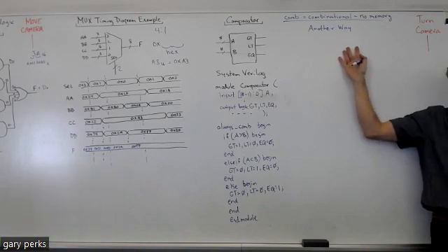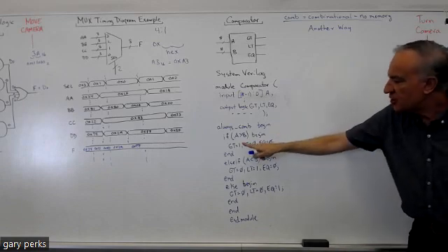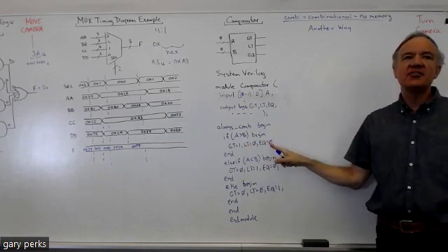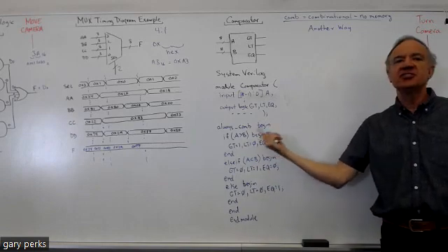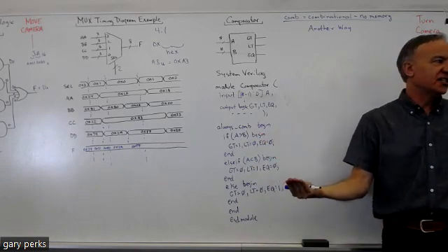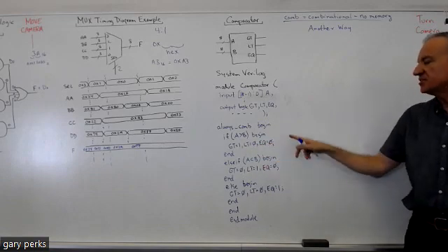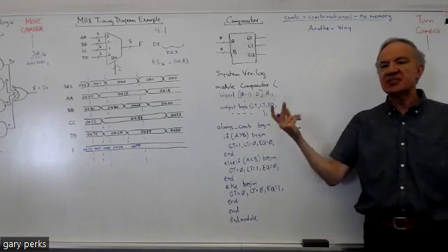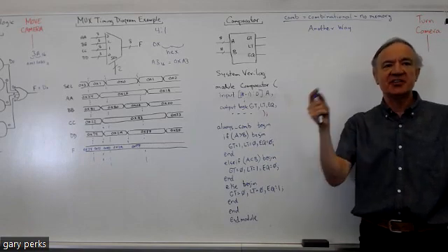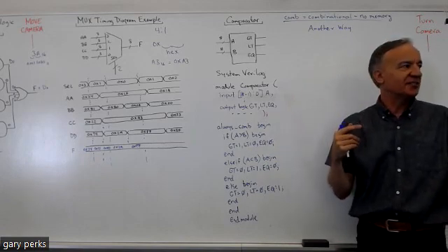If you initialize your output values to 0 to begin with, then you don't have to list all the outputs in your if statement. You can just list the one that changes. By doing that, you don't have to keep doing these begin ends, because you only need begin end within the if when you have multiple outputs. If you have a single output, you don't need to put the begin end.